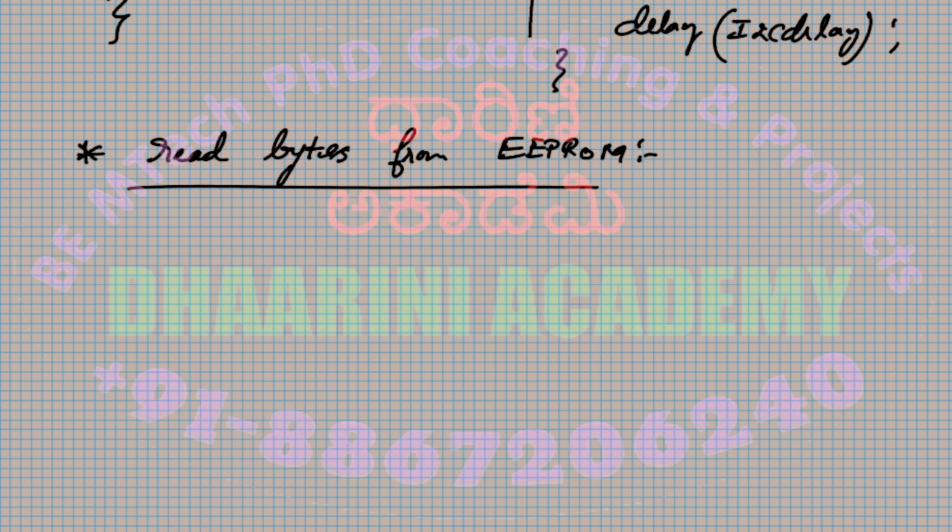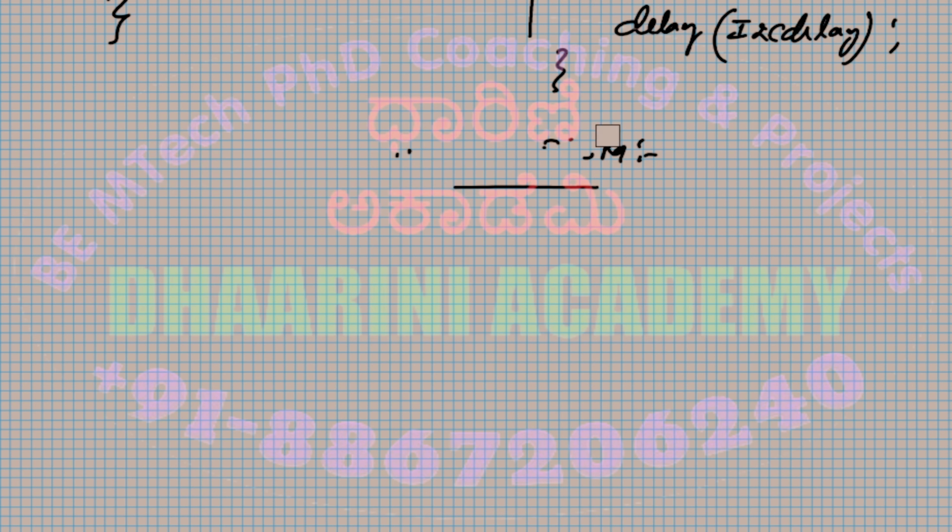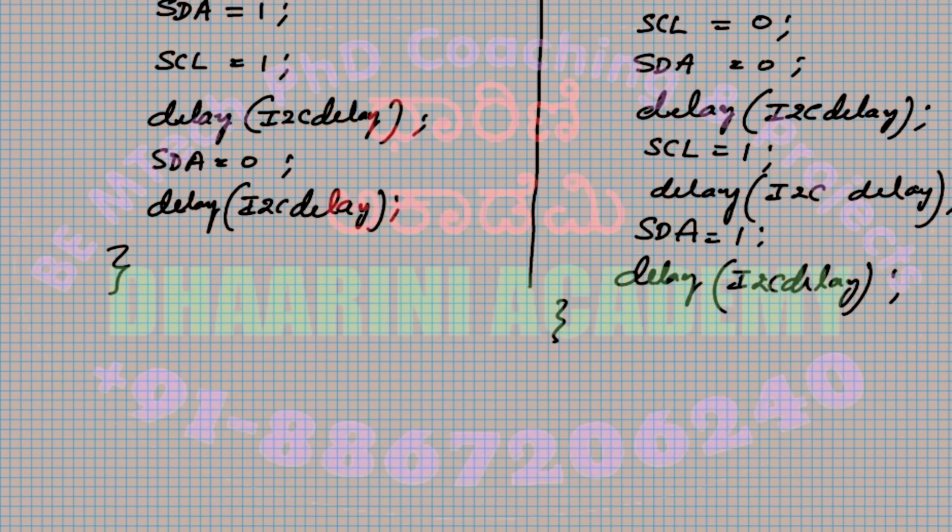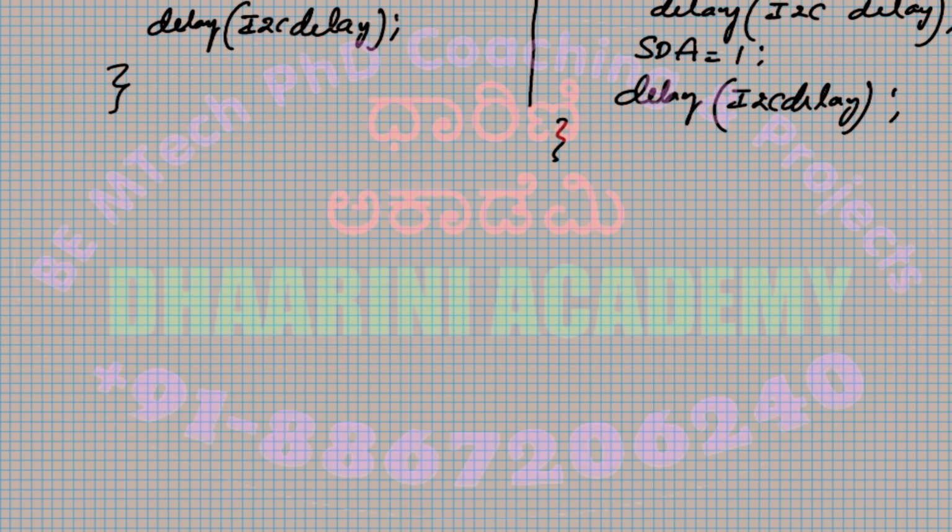Okay. So actually there is another part, I think before this I will write that because that is very useful. In the theory part we never discussed it, but this is going to happen whenever you don't get the acknowledgement in a single shot. You sent a start, saying that I want to start the communication, but none of the devices reply to that. It means you have to do what is called a repeated start. There is actually a concept called repeated start. When I discussed the theory just before, I didn't write that, but I'm going to write a code for it.